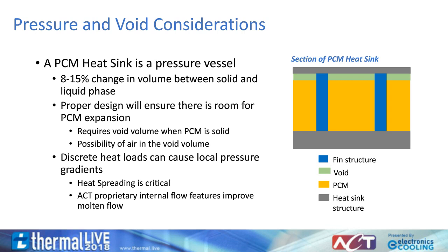One of the challenges is assuring the void volume does not cause unwanted temperature rise, and fortunately, this design challenge is resolved by proper fin design that we discussed in the last slide. Since the fins will provide a good conduction path to get the heat into the PCM, the temperature rise is minimal, no matter if there is a small void at the large heat generating component.